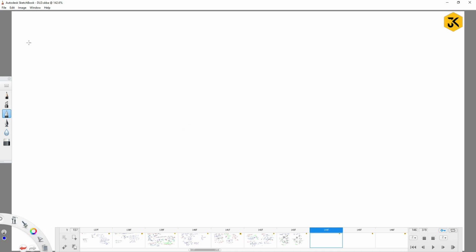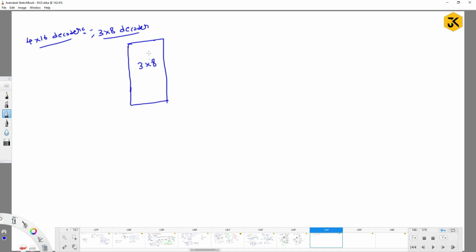Similarly, can we construct it for another kind of requirement? For example, a 4/16 decoder using a 3/8 decoder. Right? So guys, what can you do? Here you require 16 output lines. So to get 16 output lines, how many 3/8 decoders are required? Basically at the output level you require 2. At the input level, you require one more, right?